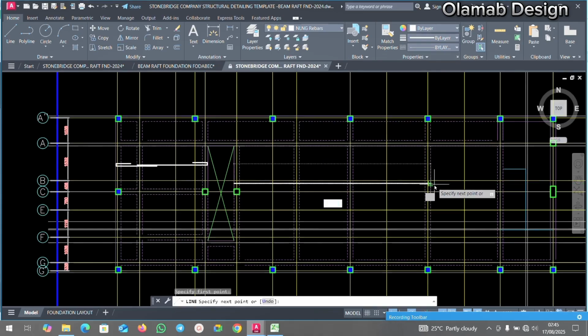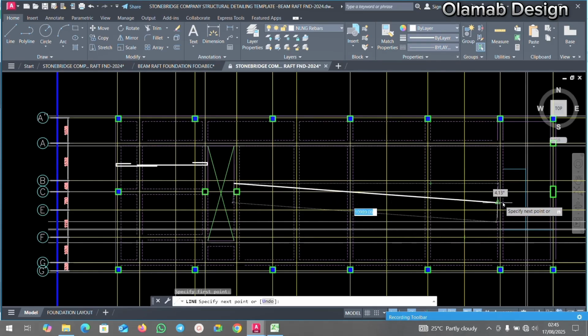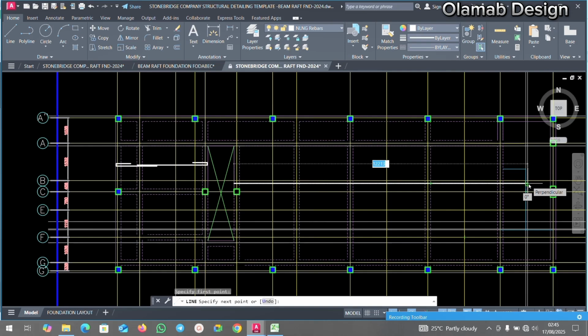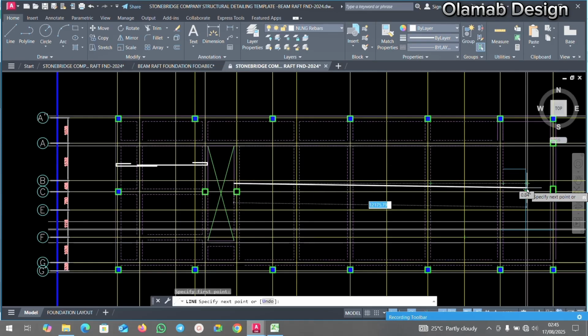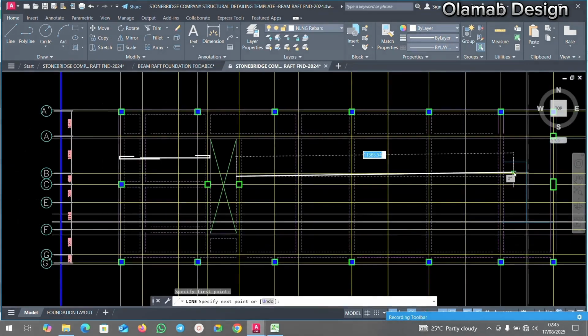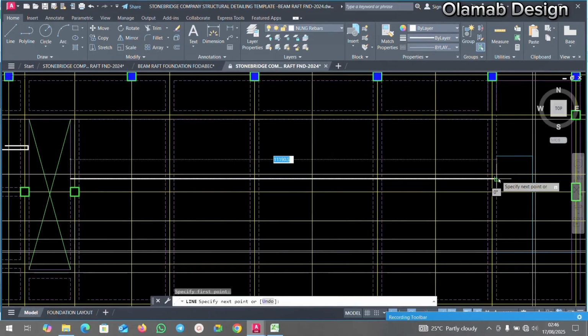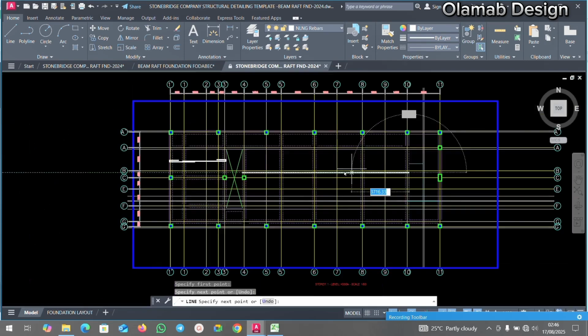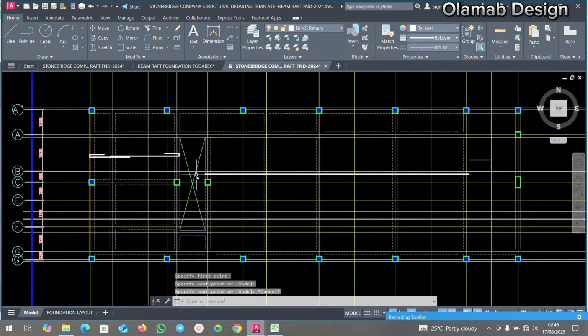We all know that our reinforcement is 12 meters. So here, if I can extend this up to 12 meters, you can see that I have 12,000 plus already. Let me see, this is 11,119, which means I can still extend to this point. But extending to this point, I already have it above 12 meters, so I can just choose to stop it right here.